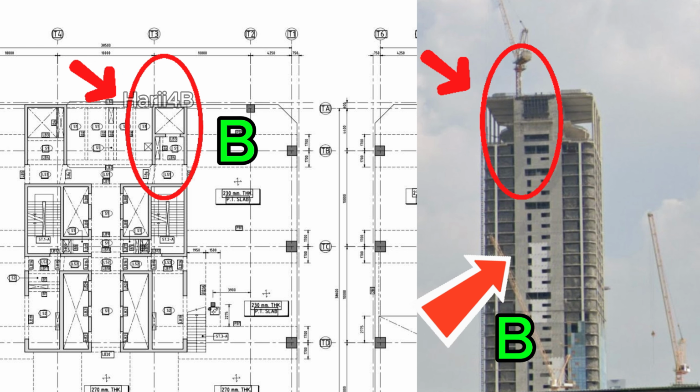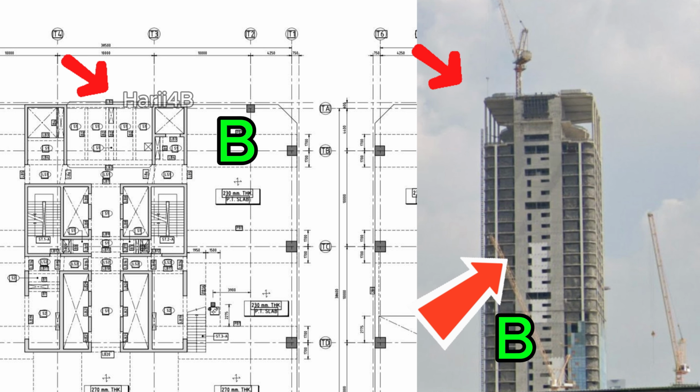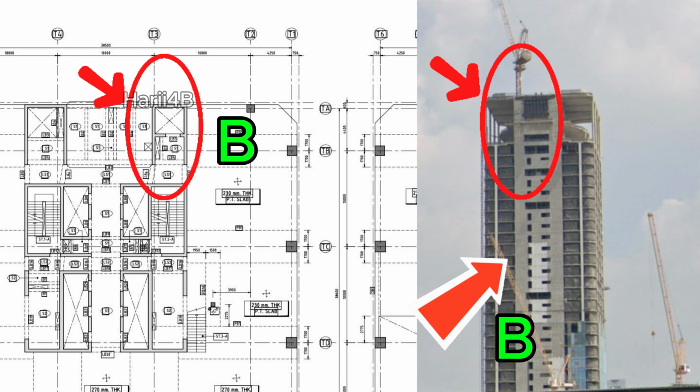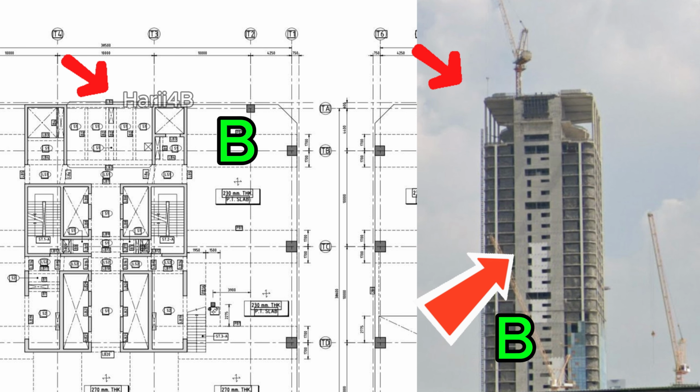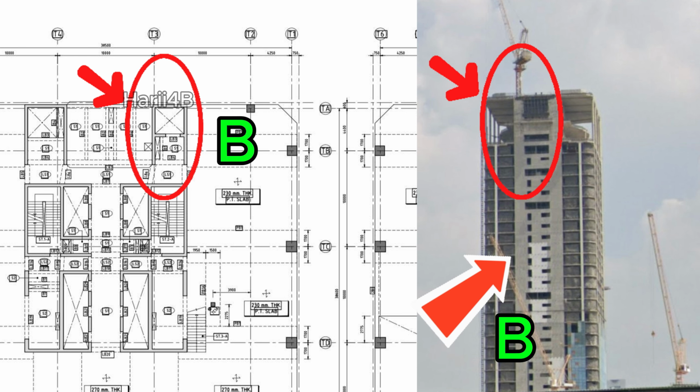Also, the oscillation or swaying motion of the tower crane induced bending moment on the support floors directly carrying the crane. The magnified earthquake-induced compressive stresses on core wall B are further magnified by the oscillation, swaying, and vibration induced by the tower crane.